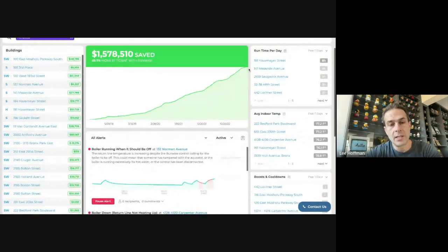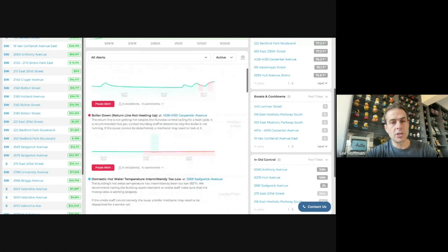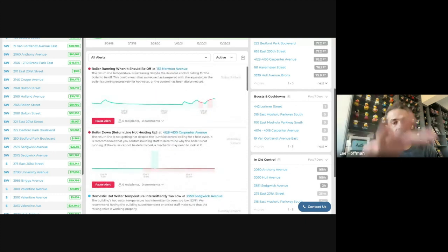So the next thing is you scroll down here. This is a common list of all the alerts in the portfolio. And this is a way to see across all of your buildings, heating, if you have water installed, whatever services you do with us, you'll see all the alerts across all the buildings right here. So here's a good example. The boiler is running when it shouldn't be. That usually means that maybe the aquastat is turned up or somebody has overridden the control.